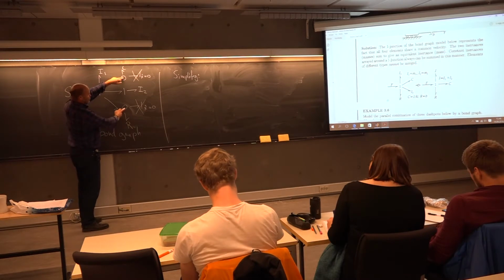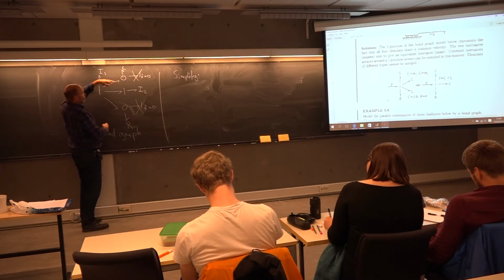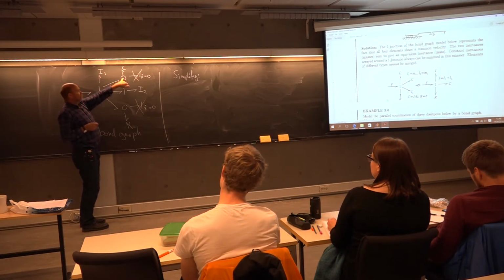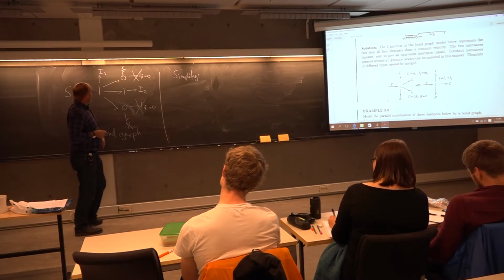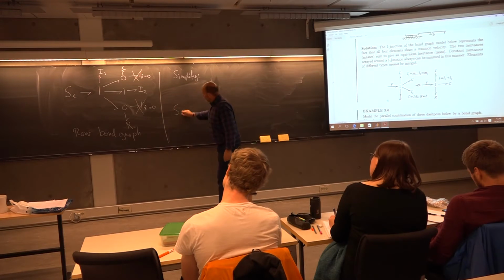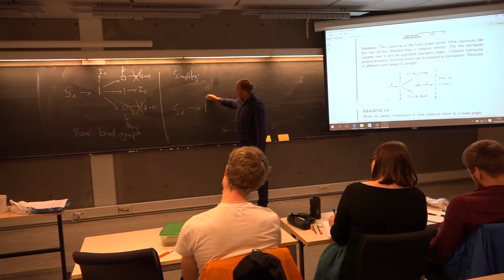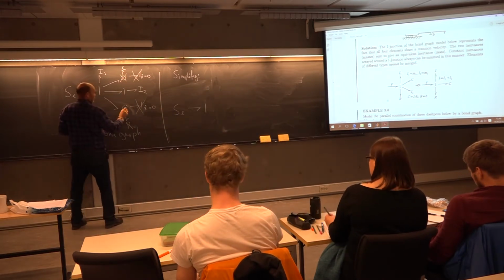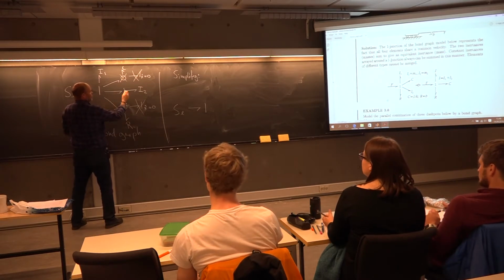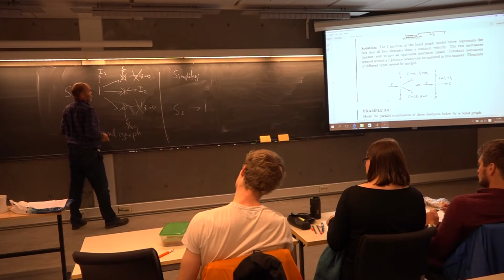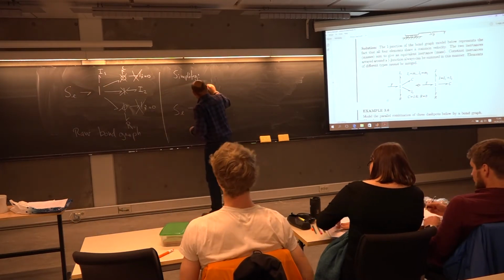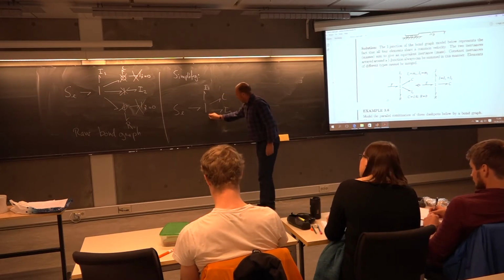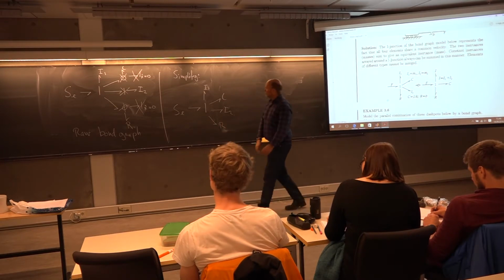Then these zero junctions can also be removed, because you have only two bonds for a junction. Then it's not a junction anymore, so you can just remove it. So the first simplification: effort source hitting a 1. Well, let's see now. We removed this, we now remove this, and also this one junction can be removed. There's only two bonds. Then we have I1, we have a C, we have I2, and finally we have R.